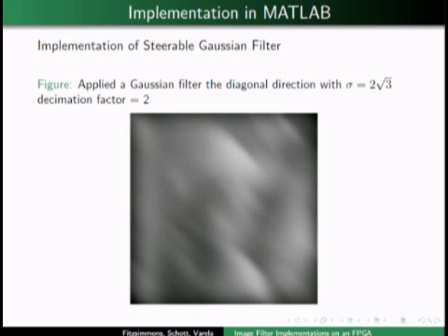But then with a diagonal direction and a decimation factor of 2, this is really the goal image we had. And you can see it's kind of blurred beyond recognition here, and that's because we are using a large filter on a smaller image. We just did that to keep in line with what we're doing in VHDL for how much resources we have on the Spartan 3 platform.